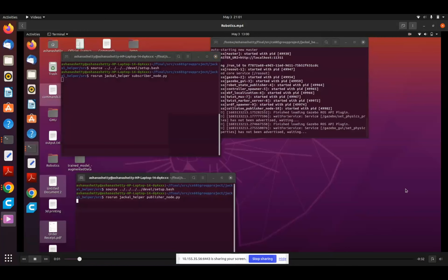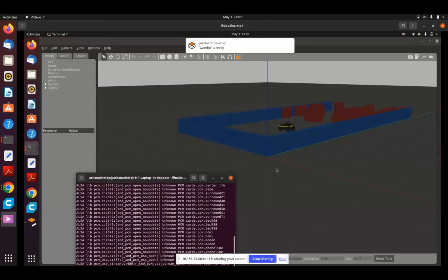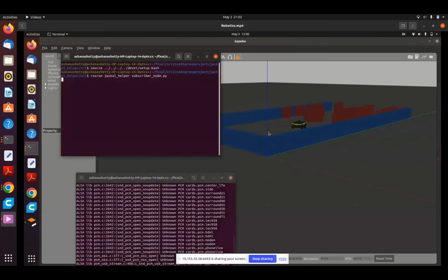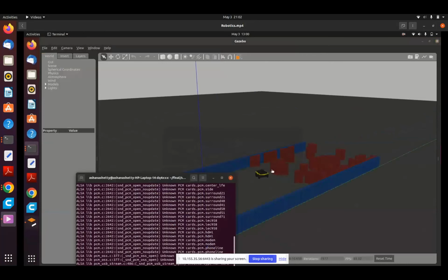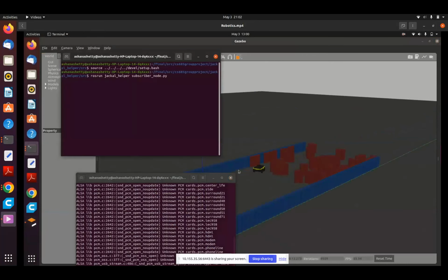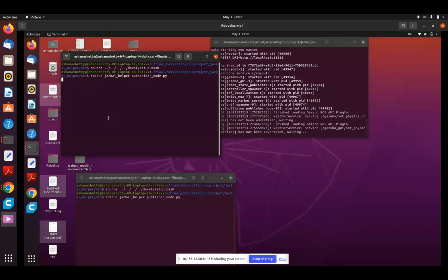But basically we are running all the nodes. So we borrowed some of the Barn Challenge worlds, and we used the Jackal robot. And so the publisher is listening for speech input. And then you could give a command like set the maximum velocity, for example. And then we have it print out to the publisher node. So it received label 9 with amount 220, which is kind of a high amount, but you probably would do a much lower amount.